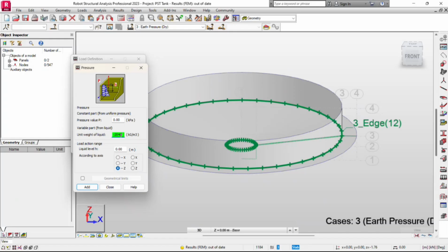Later on you will see the effect of the sign if I apply the loads. So basically it's a trial and error. If you put positive in here and your pressure goes inside the wall, which is quite the opposite because our soil is actually around the perimeter, then you have to reverse the sign. So it depends on the orientation of your wall, sort of local axis.